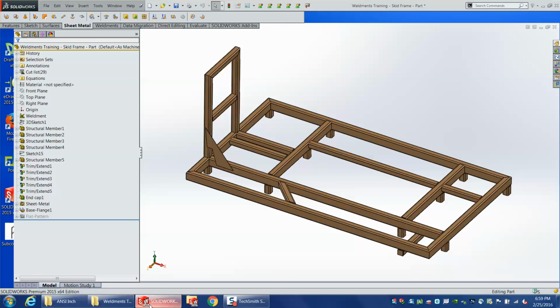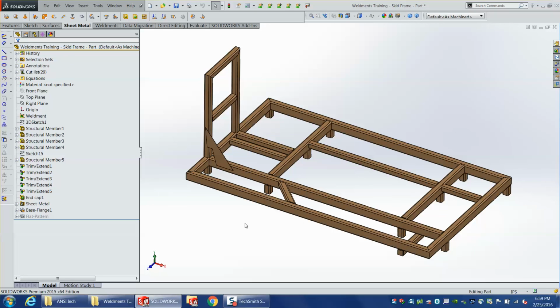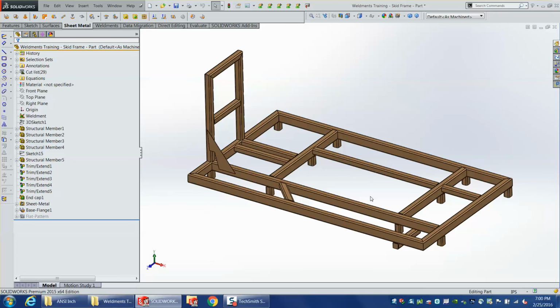How does a weldment bill of material integrate into a full machine bill of materials? You have to do it indented and then dissolve the sub-assemblies if you want a top-level parts-only list. So if you want all of your cut list members to show up in your top level bill of materials, yeah, you're going to have to jump through a little bit of hoops to get that. It's doable. Remember, it shows up as the machine, even though it's not supposed to. Did that get fixed in 2016? I haven't tested it yet. I heard a rumor of that, but I'll have to check.